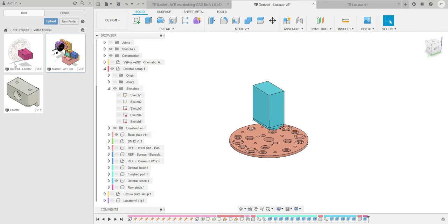So if you forget to go into that middle derived file and update it, those updates won't flow through into the file that has these derived parts in it. Hopefully that makes sense, but I'm really just saying don't derive from an already derived file. It can make things a little bit confusing. If you think you'd remember to do that, or if you think you can come up with a clever naming scheme, which effectively tells you which files you need to update, then go ahead and do that. But personally, I don't like to do it because I might not remember.